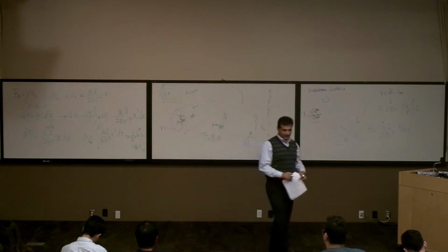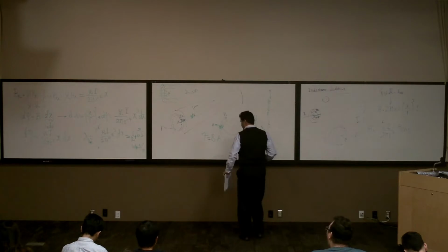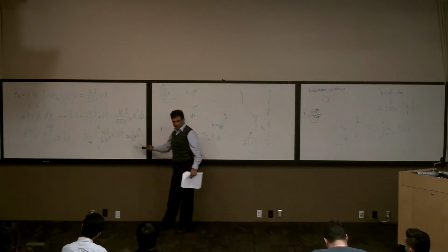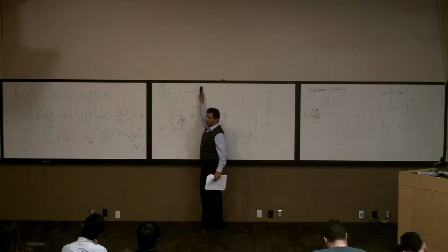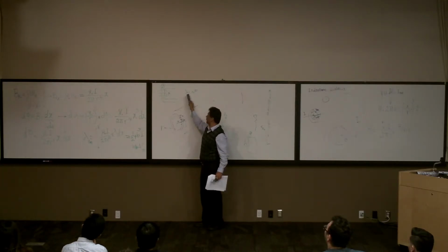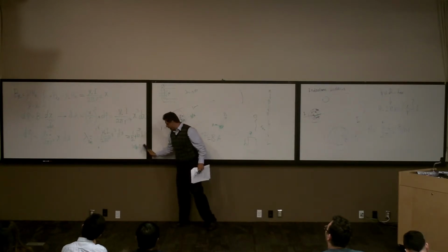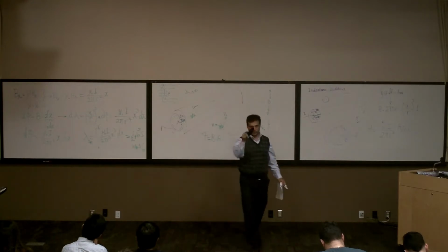Now, how much is the L? If I want to calculate L internal, how much is it? It's the Weber turn. You know where it's coming from, right? We say lambda is n phi. What's the unit for phi? It's Weber. You can remember that one from the transformer. N is the number of turns, so they call it Weber turn. And I do it over 1 meter because I'm calculating this for 1 meter of cable.